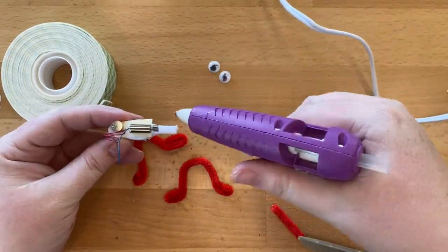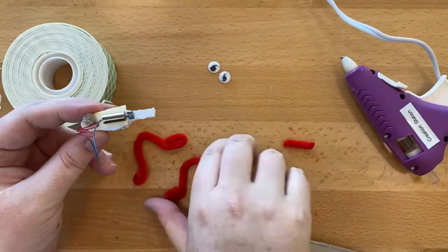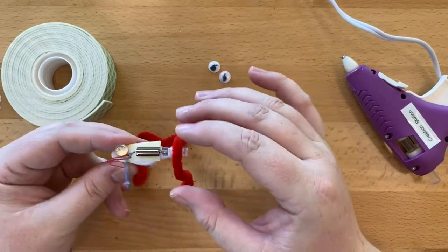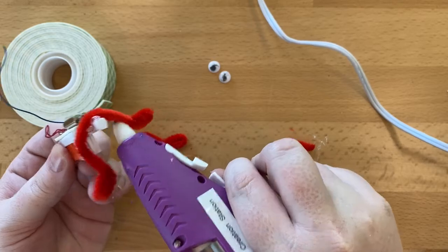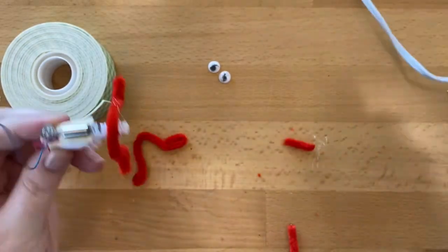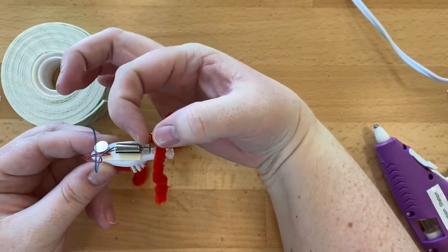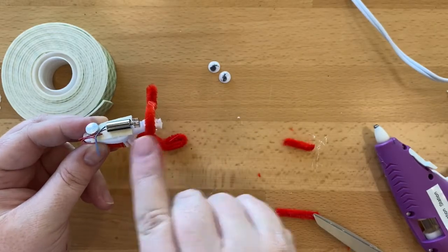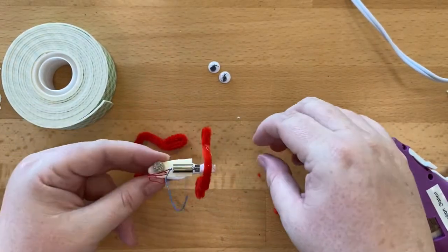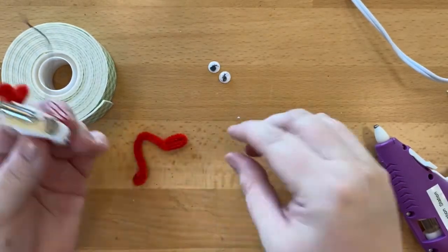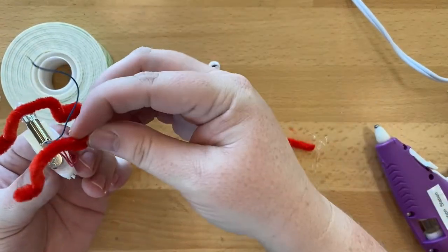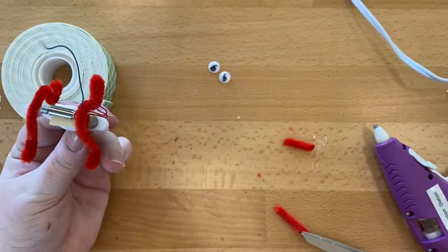Once you've finished forming your legs, take one set and hot glue them to the back of your toothbrush head. Make sure the legs do not touch the rotor. With our back legs already set, let's go ahead and place our second pair in the gap between the battery and the vibration motor.